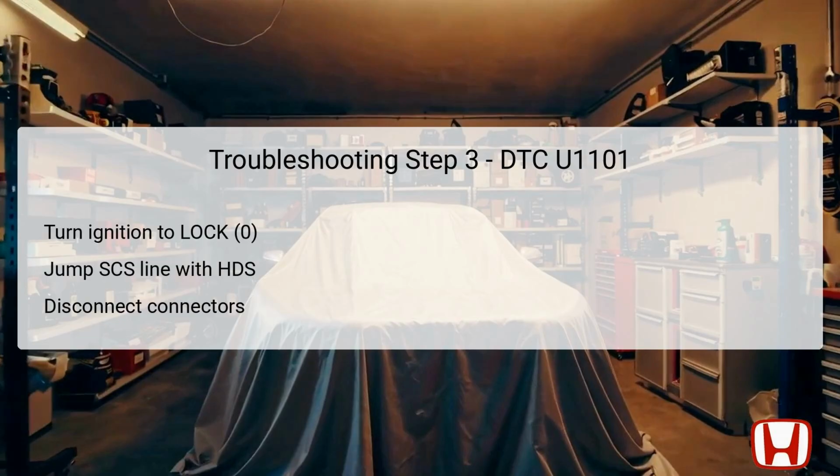Once secured, the technician must jump the SCS line with the HDS. The SCS, Service Check Signal, line jumping allows for tests to be conducted without triggering any additional fault codes. After this preparation, the technician should disconnect the engine mount control unit, 16P connector, and the PCM from their respective